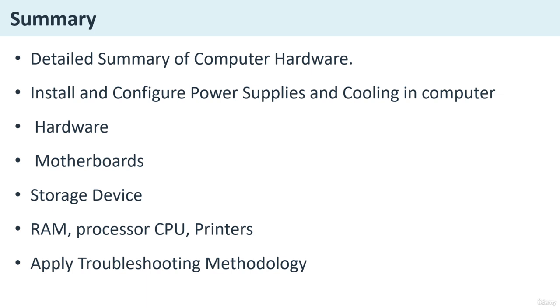Now, power supply safety features. First of all, over voltage protection, that is OVP. Here, the system shuts down if voltage exceeds the safe limit. Now, the second one is under voltage protection, that is UVP. It prevents damage from low voltage. Over current protection is OCP. It stops excessive current flow.